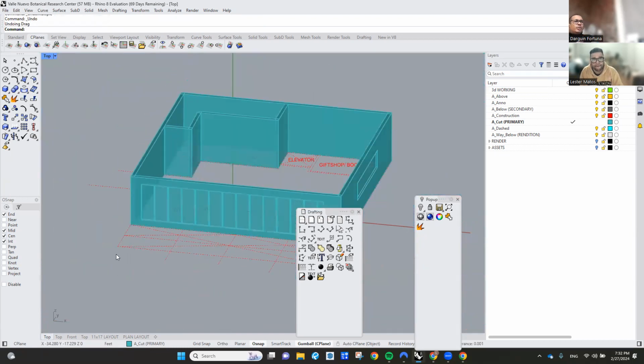So now you know how to do voids into a wall. That could turn into either a window or a door. You know how to extrude any element. So you could easily create a roof here if you felt like it. You know how to create mullions by using the contours. You got all that stuff. The precision will be given by you as a designer. I'm just telling you the tools and how to use them so that you can create it.